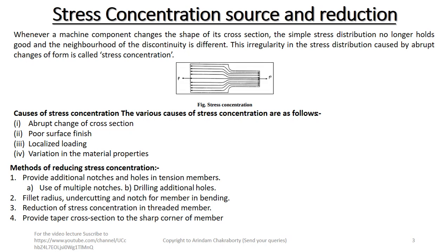I have taught it to the BTech and BSc students. What does residual stress mean? Residual stress means the stress between the boundary layers which we observe while recrystallization. After recrystallization, there may be stress that is completely internal, which you cannot observe from the outside. So there are internal tensile or compressive stresses, which are termed residual stresses.